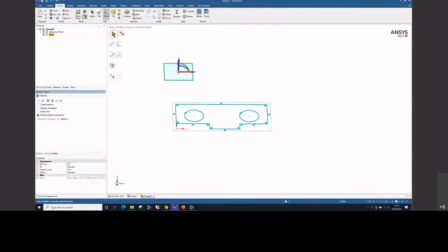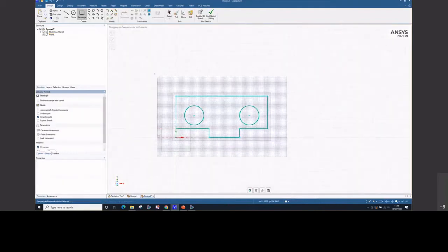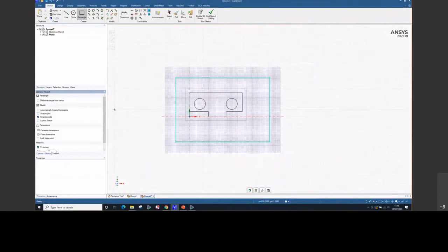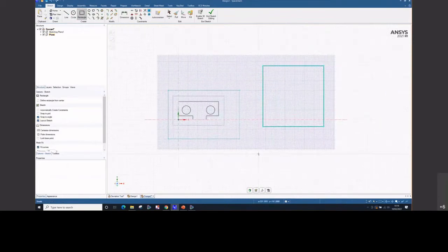So I click on this plane and I go into sketch mode. I then create a sketch. It's just going to be a block. And one thing I like to do is actually sketch with layout sketches. So I'm going to create two shapes, one with layout sketch ticked, and we can see that there. So literally two boxes. If I want to end the sketch editing,